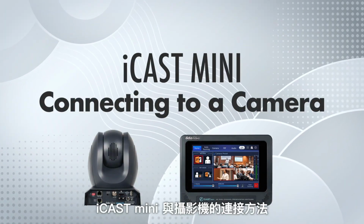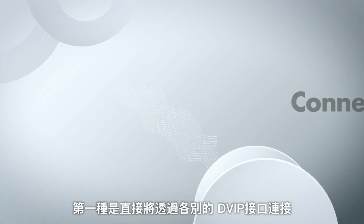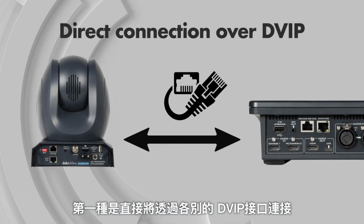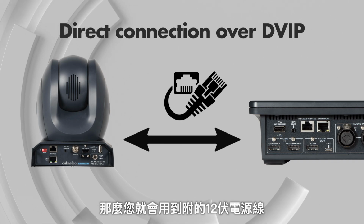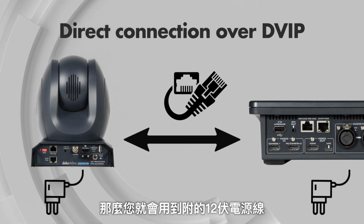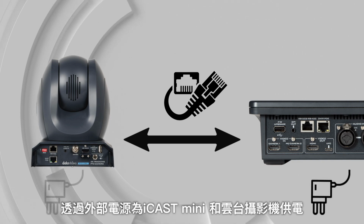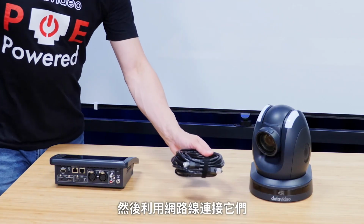For connecting the iCAST Mini to a camera, the first way is to directly connect the iCAST Mini through the DVIP ports on each device. So you would use the included 12-volt power supplies, the external power for both the iCAST Mini and your PTZ camera, and then connect them using an Ethernet cable.